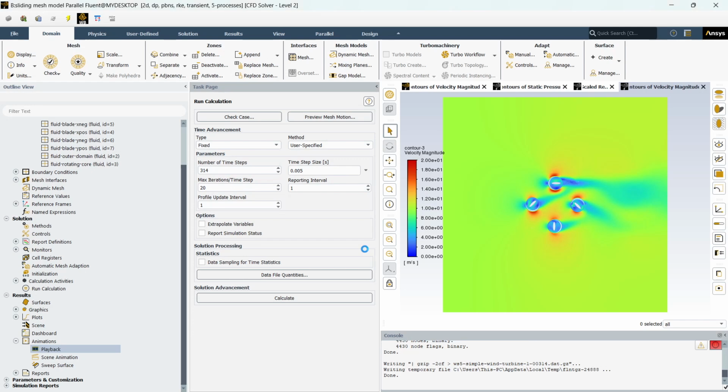We've learned how Fluent can handle rotating regions dynamically without needing to remesh every time step. This is thanks to the use of non-conformal interfaces, disconnected cell zones that Fluent treats as rigid bodies. And remember, if the geometry deforms or changes shape, Fluent also offers the dynamic mesh model to handle such advanced cases, automatically adding or removing mesh cells where needed. And with that, this project has come to an end.